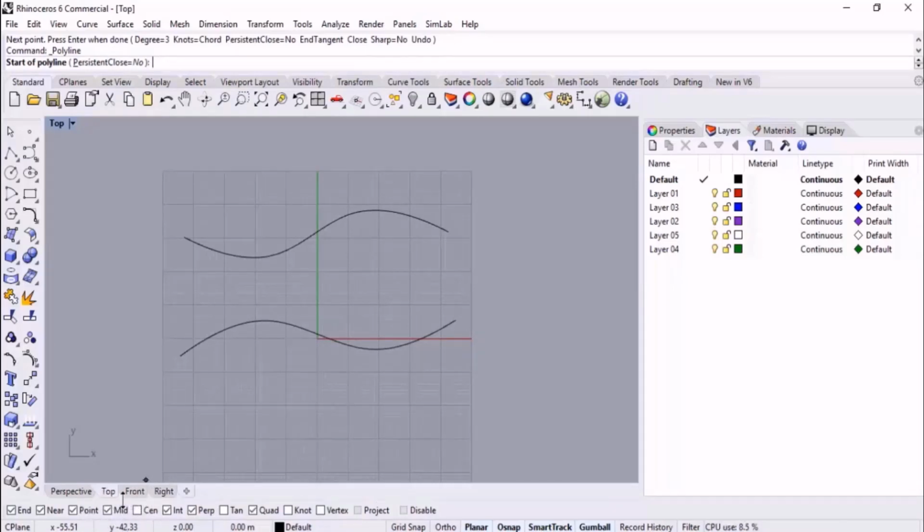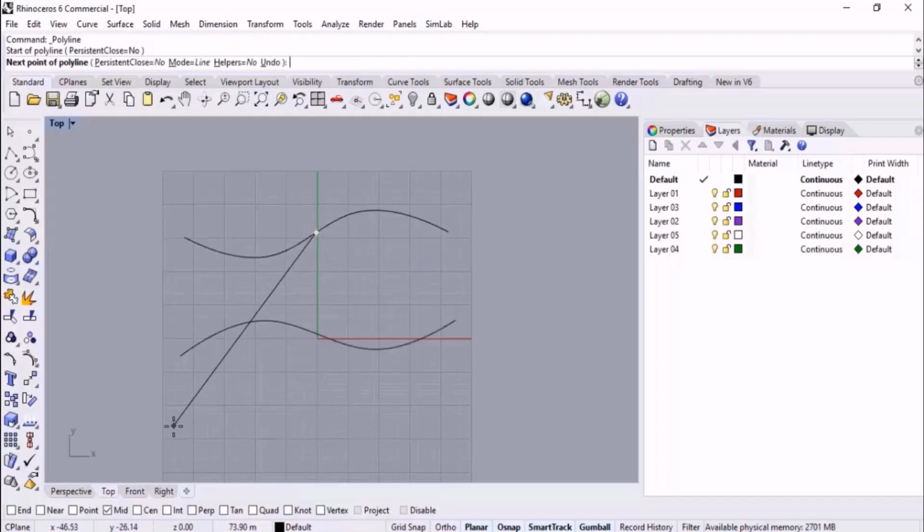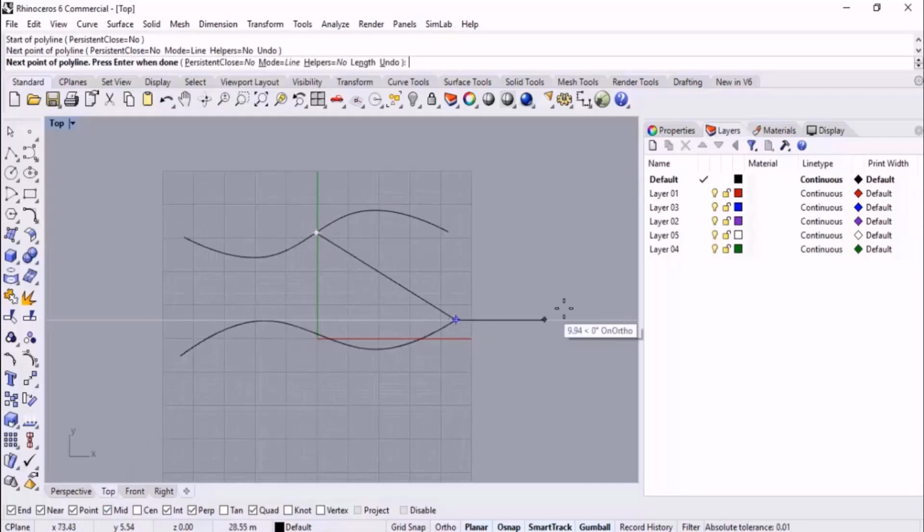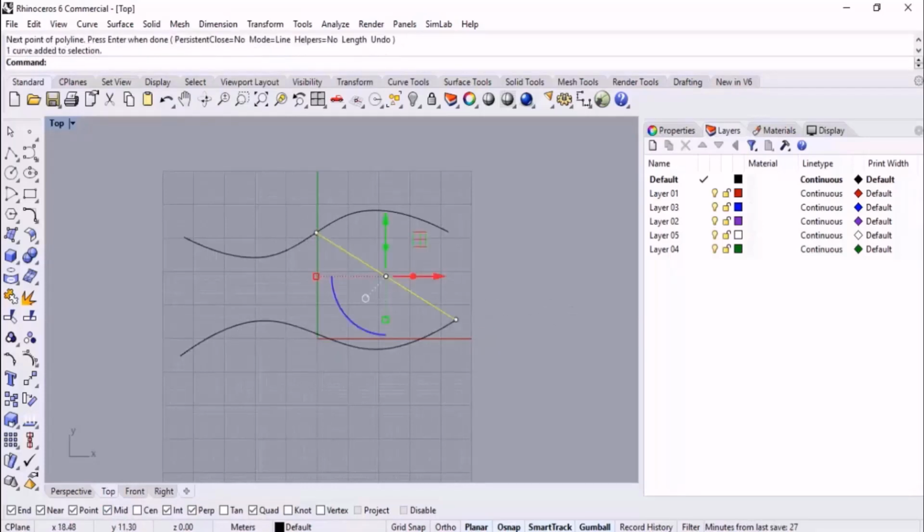As the first point that I have mentioned before, if you wanted to have only one of the object snaps activated, we use to right click on the desired object snap. For example, I right click on the midpoint, it deactivates the other snaps temporarily. Then we can use the midpoint of the curve. Then if I want to use or need the others, I right click on the midpoint, then the other snaps will be activated too. But here there is another approach, so watch this part carefully.